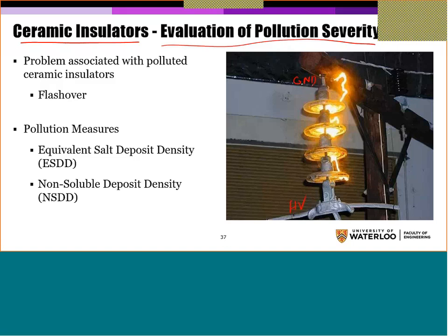It means that once there's a flashover, the flashover will wipe out all the pollution, so the insulator comes back clean. So in many cases, this is not sustained. It happens once or twice, and then it removes itself. This is why we use a recloser. The recloser opens and closes automatically, so that if the fault is not permanent, it will clear it. So you don't need to permanently open the circuit breaker. Okay, so this is flashover. Now, how is this happening because of the pollution?